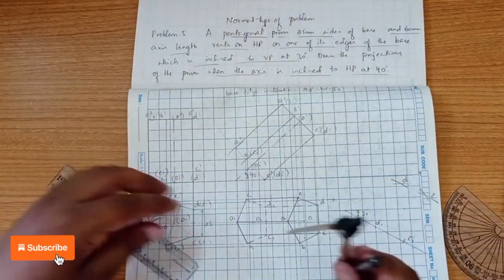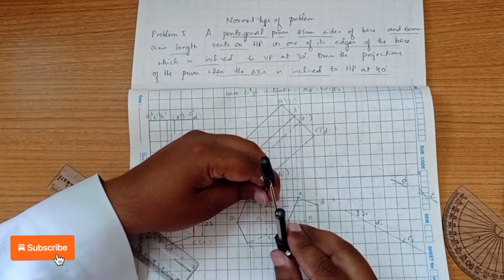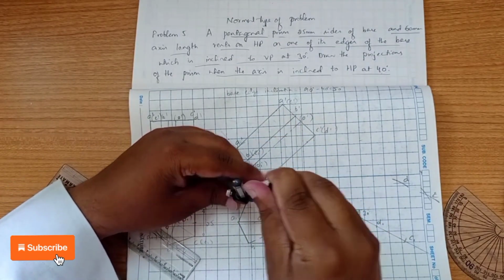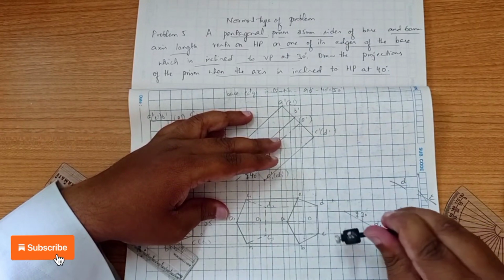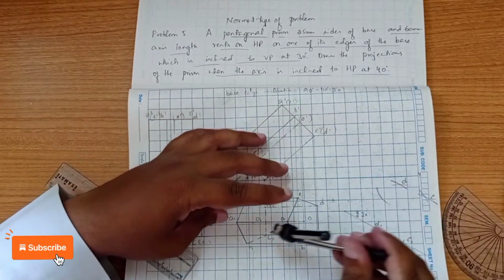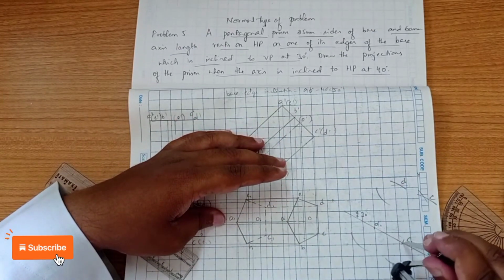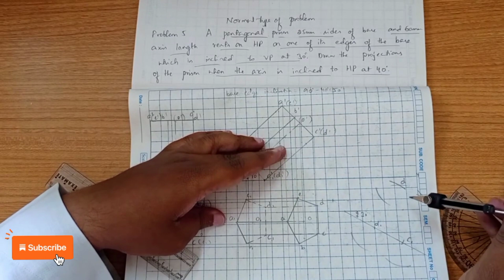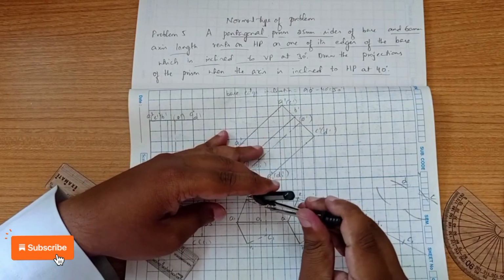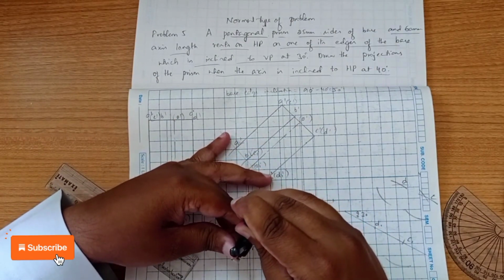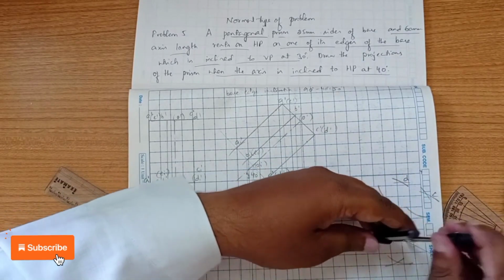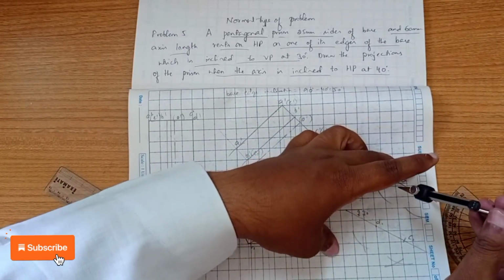Using compass we have to construct two pentagons here. So the lengths will remain the same. You just measure it. D1 and D1 it is exactly equal to D to E and C to B. Okay, C1 to B1. So those are all the same lengths. That's why I am taking only one length and cutting the 4 arcs, because all those 4 lengths are the same. Now it is reverse. Okay, D1 to B1 if you measure, that will be used for D1 to B1 and C1 to B1. Okay, that will be the same.